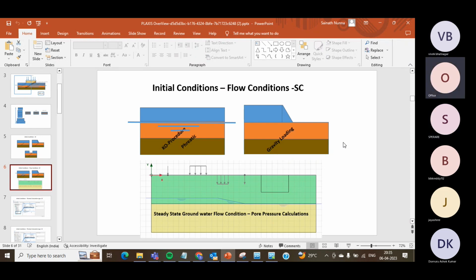Okay, then it is taking, let us say, a weighted average or something, in which it is ignoring the variation in the water table level from borehole to borehole. When your initial borehole water level is not always straight, if you have 10 boreholes, that can happen. Not necessarily 1 meter in one borehole and 3 meters in another, but there can be variation. That variation is possible.